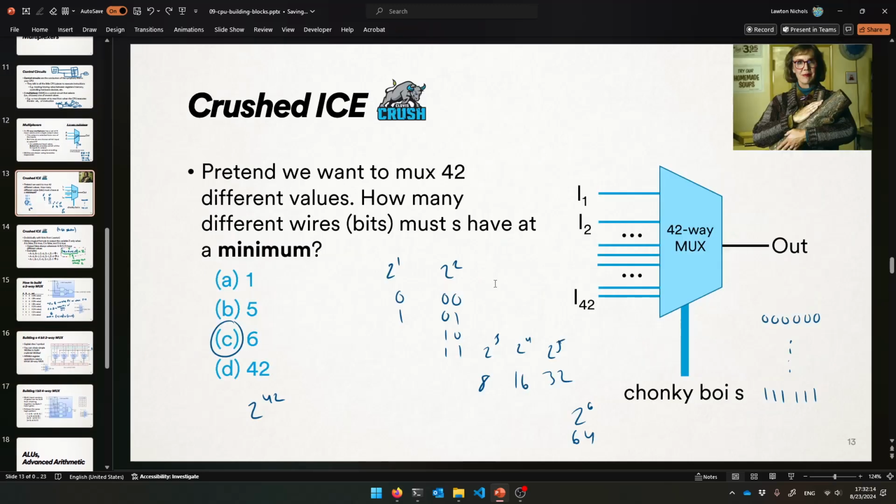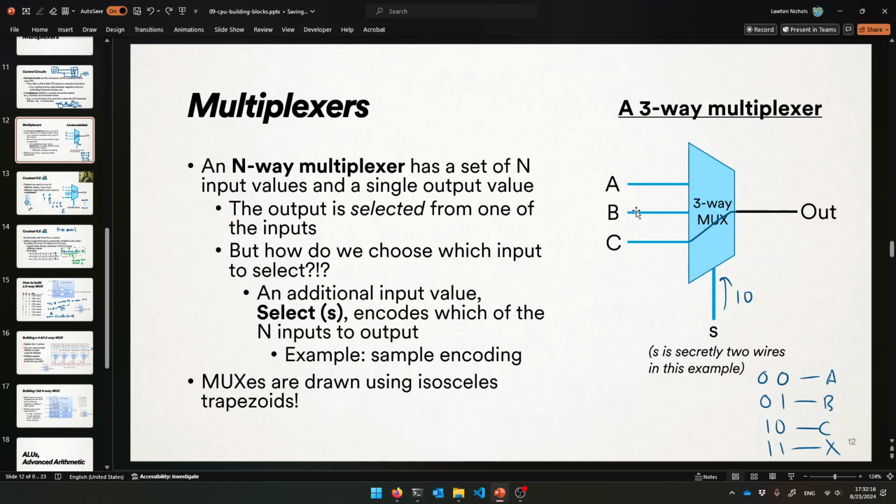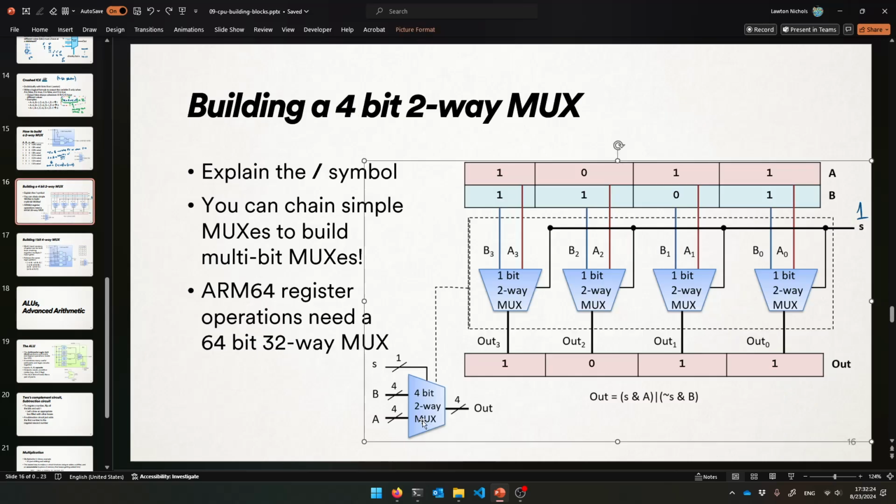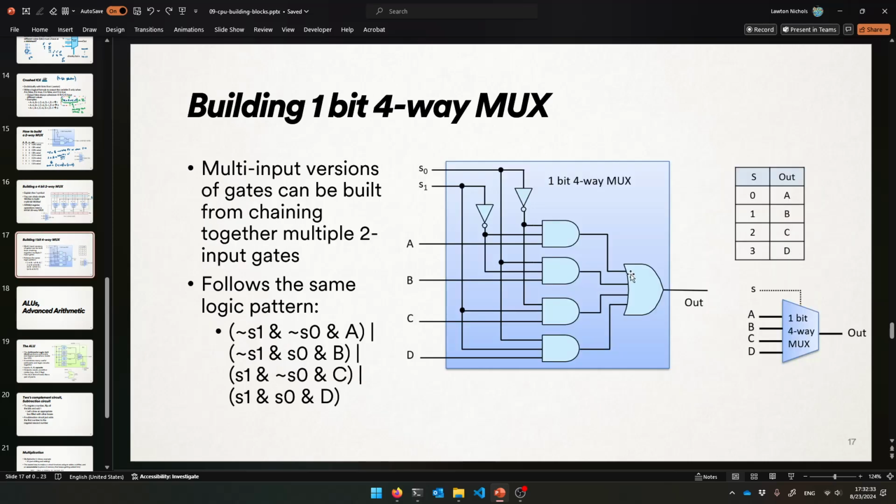And I encourage you to think of how would you build this 3-way multiplexer now with 2 input S wires, like S1 and S2. See if you could encode it. I think you could. So yeah, we can start zooming out again, and now just the magic of abstraction takes over. It's really, really cool. That's how it works. So yeah, let me try now to build for you a 4-way multiplexer.